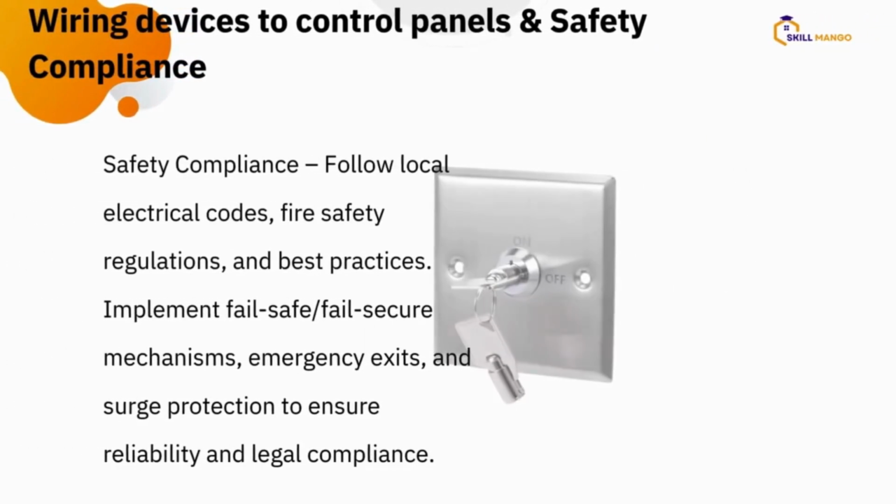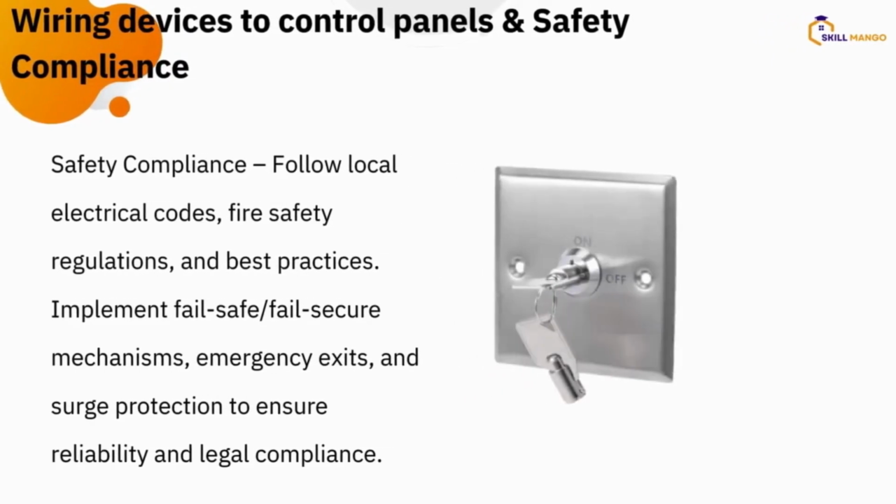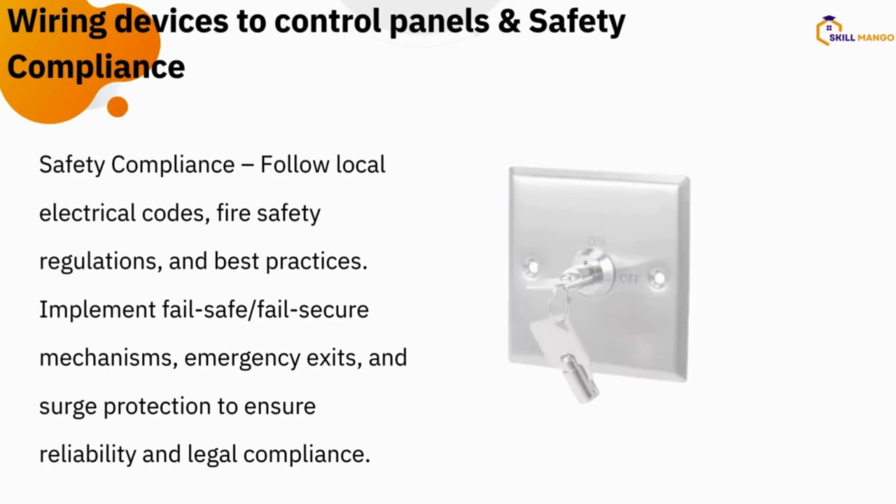Okay, so safety compliance also, we usually advise that you follow all the safety compliance on the wiring. Ensure you use original quality wire. Wires should not be exposed, they should not be open. Any cable that is open should be well taped and well managed inside like a box or inside the trunk, so it won't shock people. It will not touch each other. When the cables touch, because of the voltage passing through these cables, it can lead to them sending the wrong signal or current to the system or even burning the system. So all these things have to be checked.